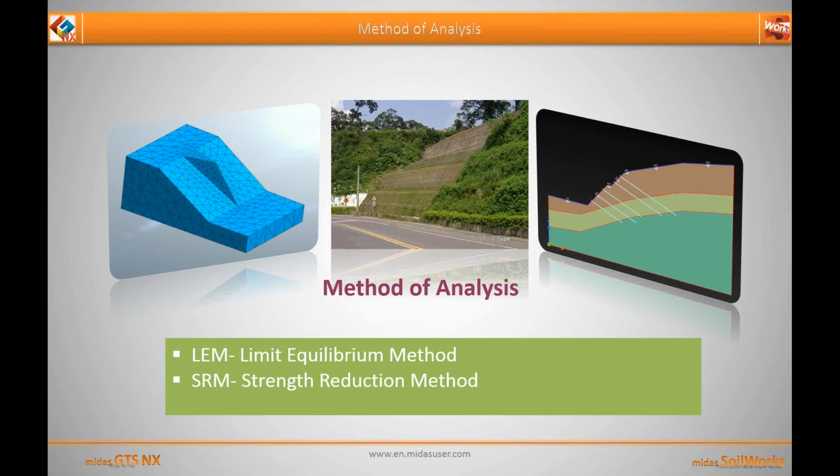Now let us talk about the various methods of analysis available to us. First is the LEM, that is the limit equilibrium method. I think most of you are very familiar with this method. The next is the SRM, that is the strength reduction method or the finite element method. I will be dealing with both these methods in detail today.